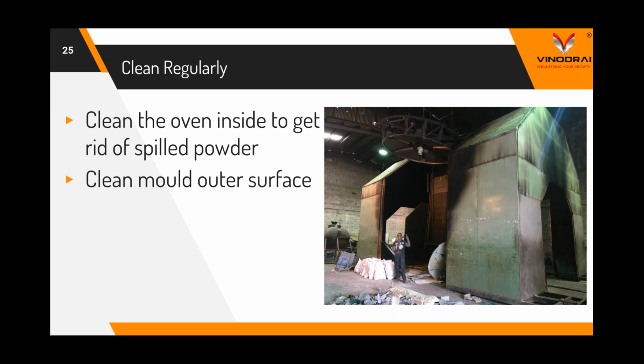Cleaning the mold outside the oven is also a process. Like you can see in this image, it is a very tacky mold which has not been cleaned for a long time. Such dust deposition and powder deposition on the mold acts like an insulation layer and decreases the rate at which the mold is heated, which is not recommended for us. So cleaning the mold regularly would result in the mold being heated faster and less energy being required to heat the mold, thus saving us a little bit of fuel.